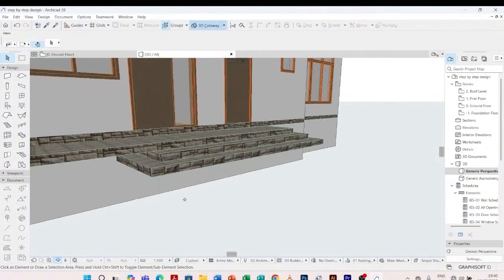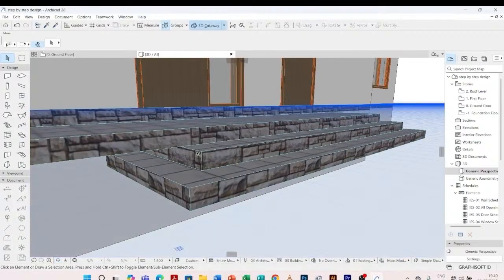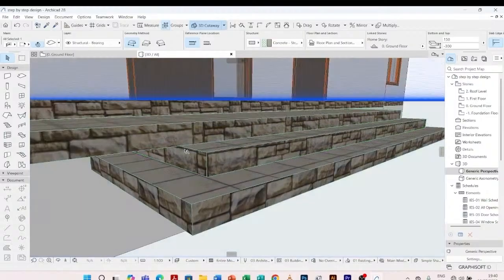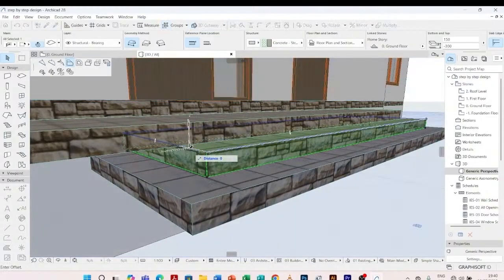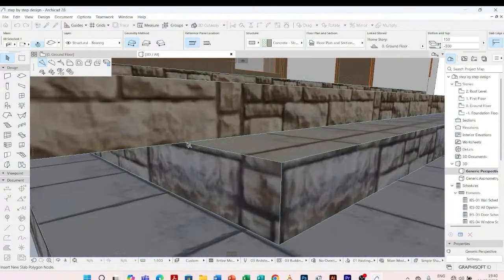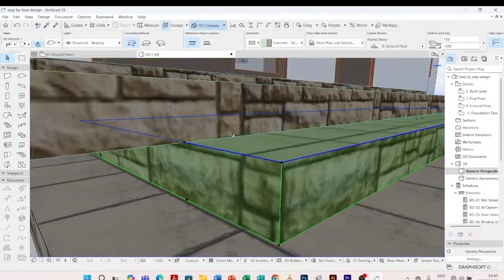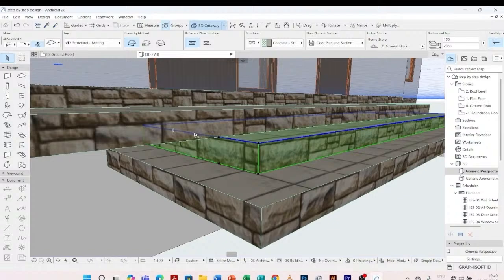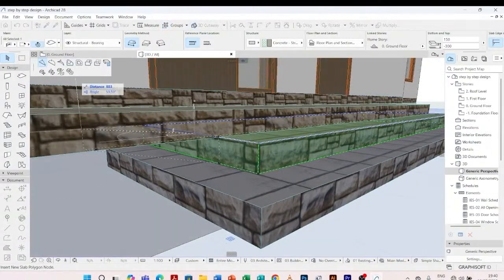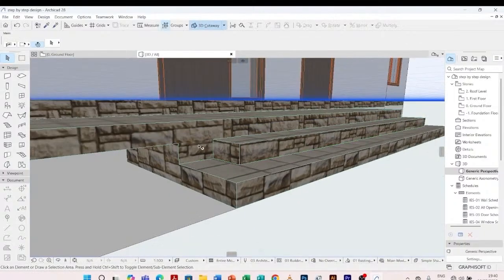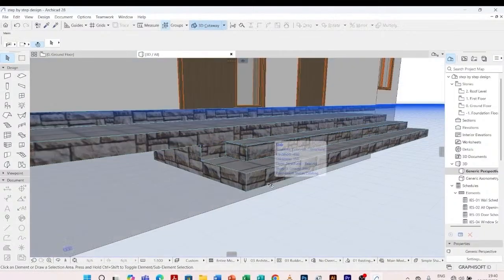So I need to cover up this gap. What do I do? I click on this slab. I'm going to add a node. I click on this blue line. Then I come to this first point which tells us to insert a new node. So when I click on it, I come and insert. I hold on to my shift. I insert my node here. So I come back to this blue line. I want to move this one, and I offset the edge. I offset it to this. While I hold on to my shift, I pick this corner. I have something like that.